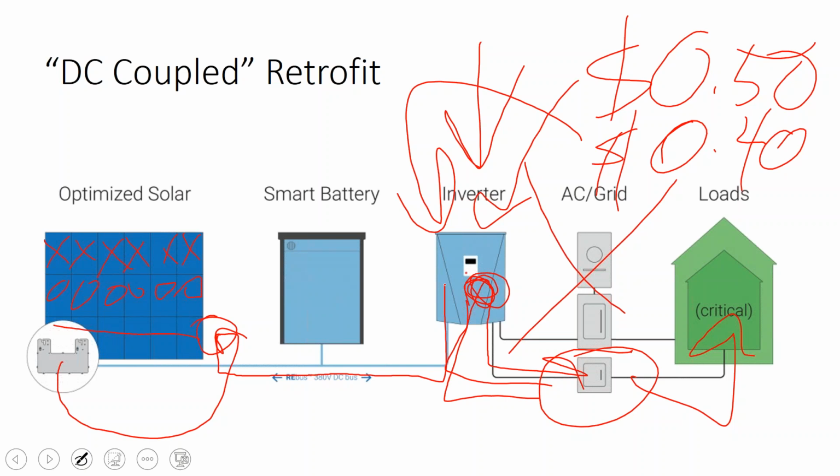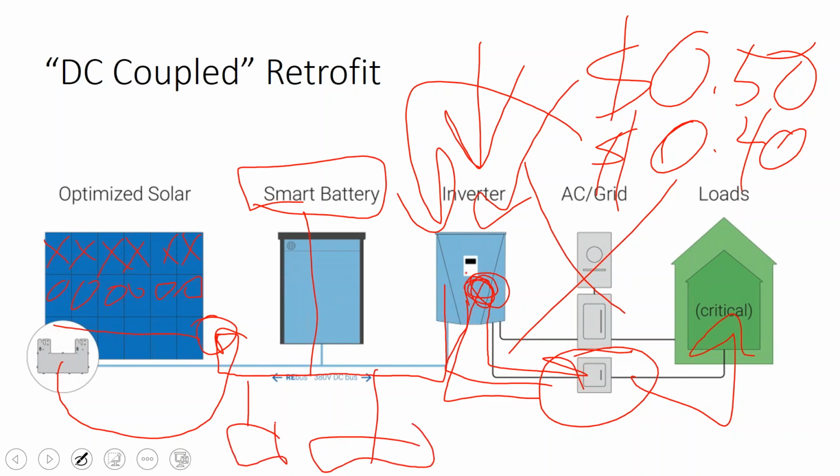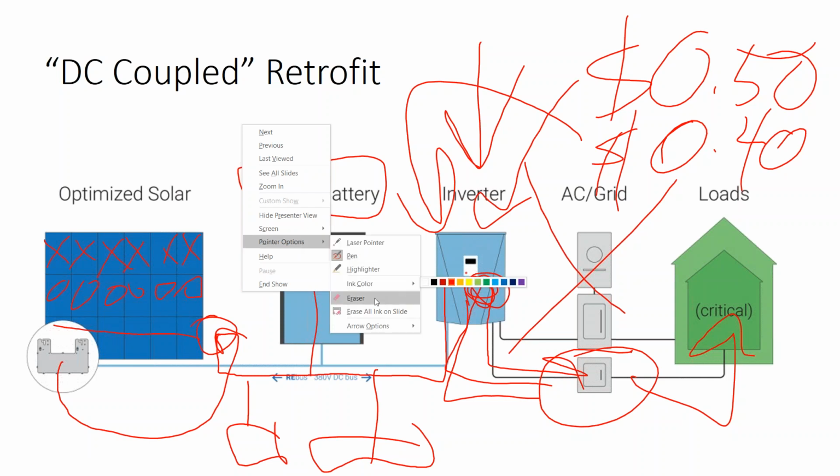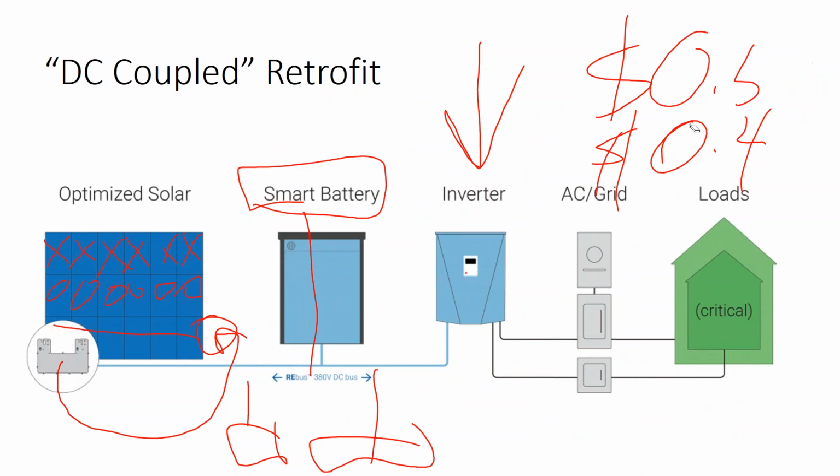Where Pika is taking it a step further is they've developed a battery management system where they can just plug in multiple batteries anywhere along this DC bus and combine multiple battery chemistries together. So you could have, theoretically, a lead acid battery providing your base energy use cheaply, and then a lithium ion battery coming in to manage the spikes and surges in your electric load. This is all kind of the future of the industry. A lot of these design concepts are not being supported by the battery inverter manufacturers on the market. That doesn't mean installers aren't asking about it.